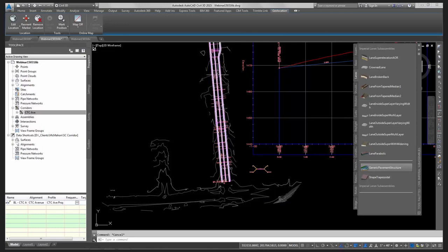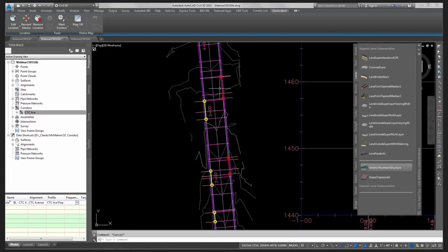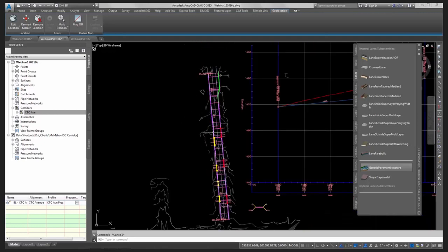Without the conditional, it would have been a region for up in here, another region for this driveway, another region for where they overlap, another region here. So we're looking at 1, 2, 3, 4, 5, 6, 7, 8, 9, 10, 11, 12, 13, 14. I'd be looking at 15 regions without conditionals to go from full curb to surmountable curb. Hey, I love corridors that have one region. 15 can be hard to maintain and keep track of. One's definitely much better, in my opinion.